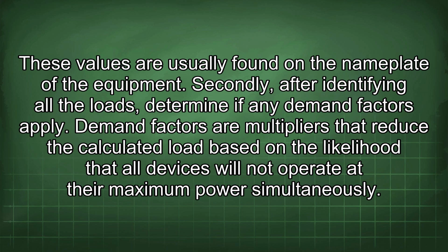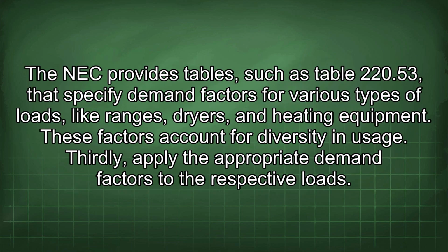Secondly, after identifying all the loads, determine if any demand factors apply. Demand factors are multipliers that reduce the calculated load based on the likelihood that all devices will not operate at their maximum power simultaneously. The NEC provides tables, such as Table 220.53, that specify demand factors for various types of loads, like ranges, dryers, and heating equipment. These factors account for diversity in usage.